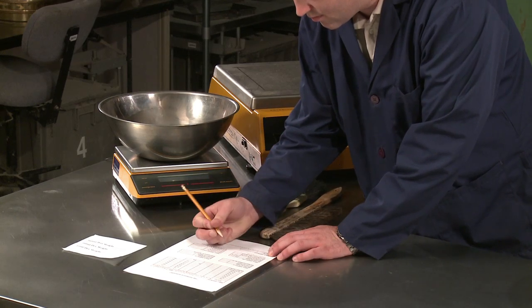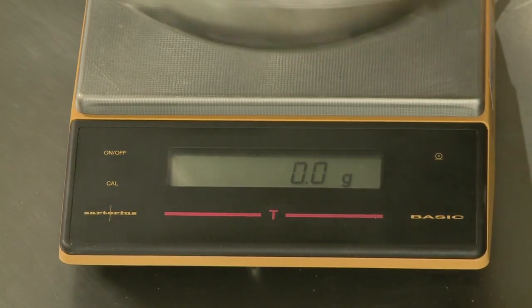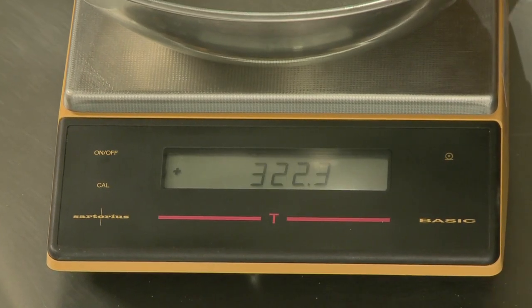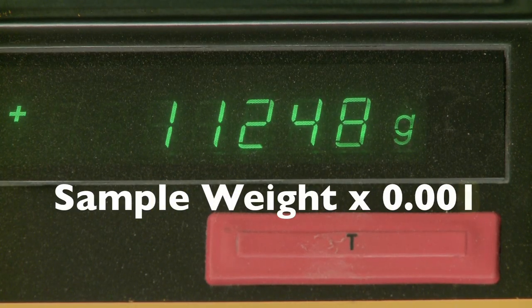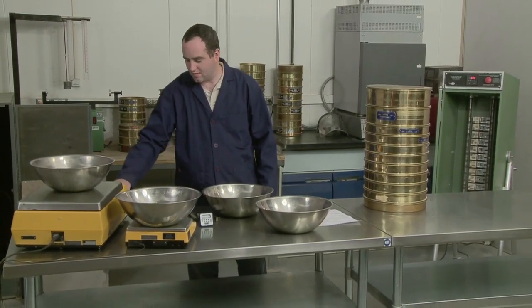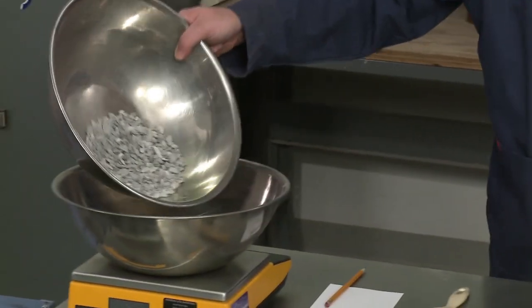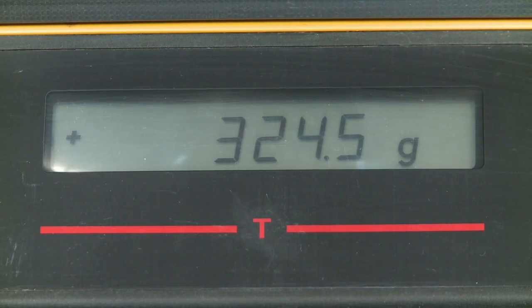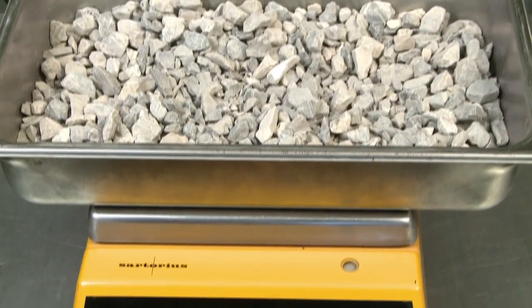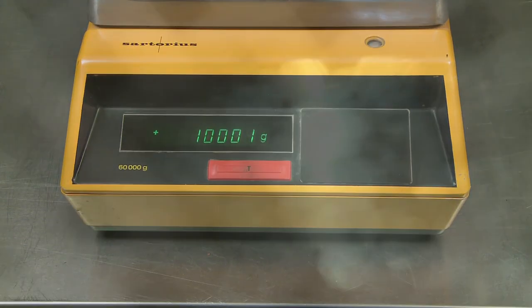To determine the required accuracy of the balance, that is, to how many decimal places the scale must display, multiply the sample weight by 0.001. The resulting product will determine the largest interval that your scale must accurately display. For example, a 100-gram sample must be weighed on a scale accurate to 0.1 grams, while a 10,000-gram sample requires a scale accurate to only 10 grams.